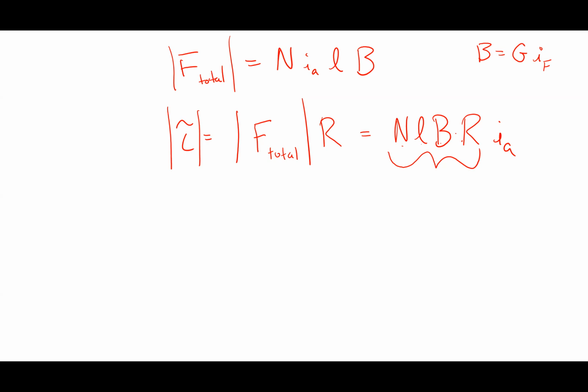This guy's meant for like half a volt. So he's kind of screaming. What's the screaming? Well, part of it could be the flux is high, right? So it could be the iron making some noise. But that main noise is the friction of the brushes, right?